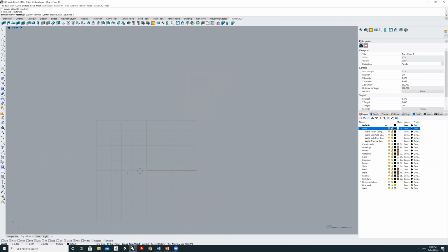And then what Rhino asks me to do is to position my cursor somewhere and start declaring the dimensions of that specific rectangle. To be precise, I'm going to input, just by using my keyboard, 0, 0, 0 as the starting point, and then you can see that my cursor is now locked on the 0, 0, 0 point, which is our origin, right? And then I'm going to click again, and I'm going to pass through the command line the dimensions of the grid, right?